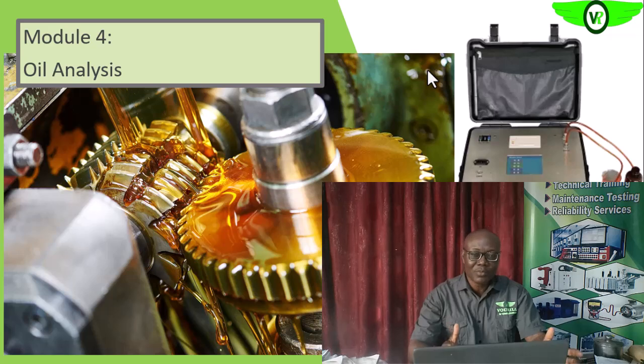So with all of these condition monitoring technologies, you will observe that before the condition deteriorates to the stage that you can feel the heat, or the vibration has increased, or before it can impact the vibration of the equipment at the location where you are collecting the vibration information, or before the anomaly will show up in your thermogram, some level of deterioration will have taken place, especially when you are looking at internal combustion engines, compressors, and other equipment whose internals do not have a connection with the external body of the equipment where you can take that information.